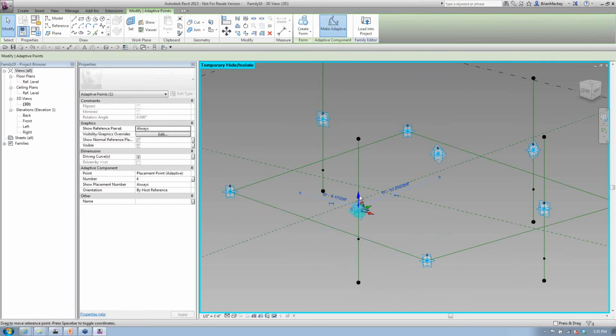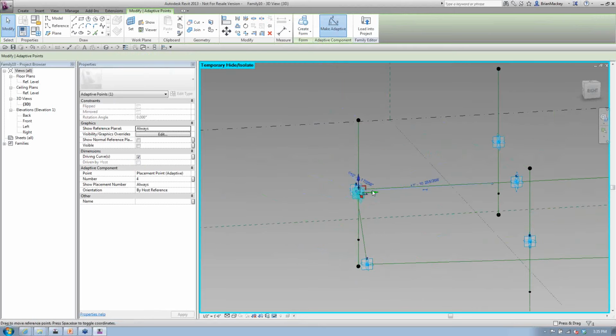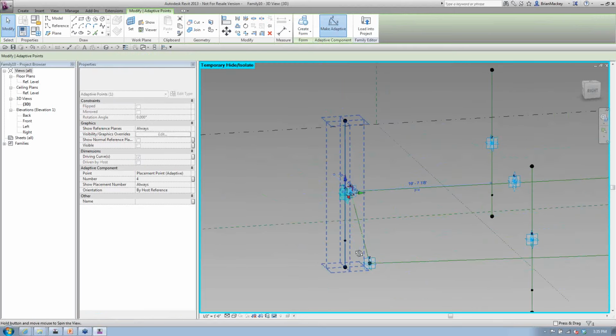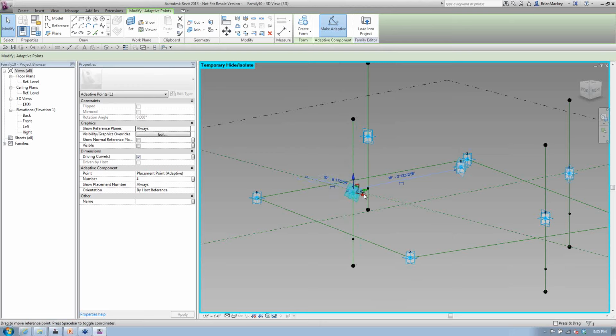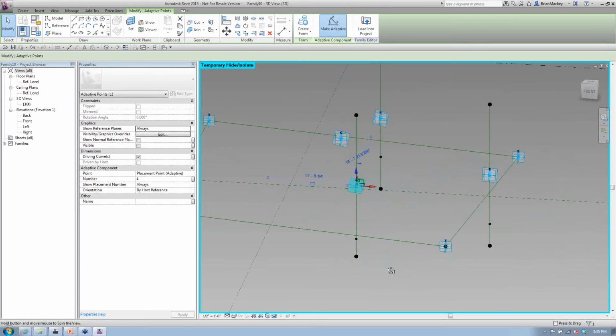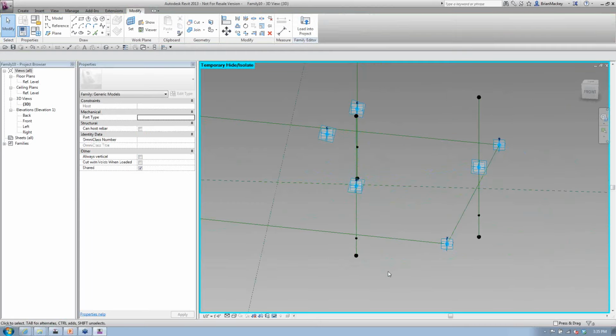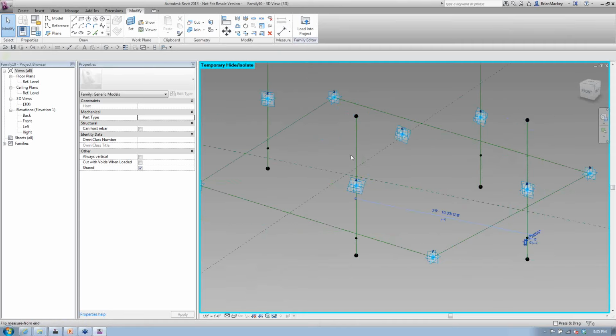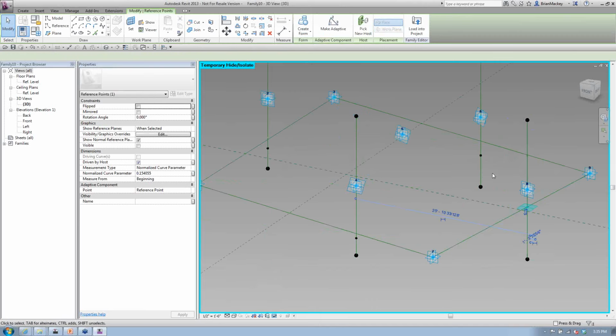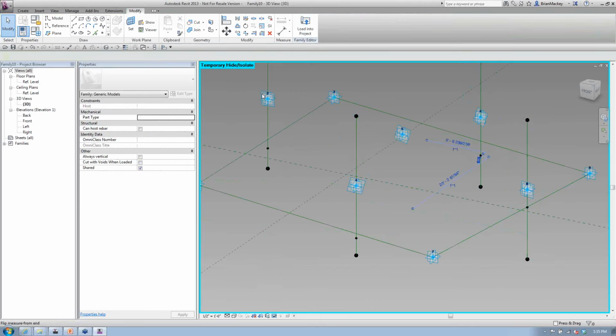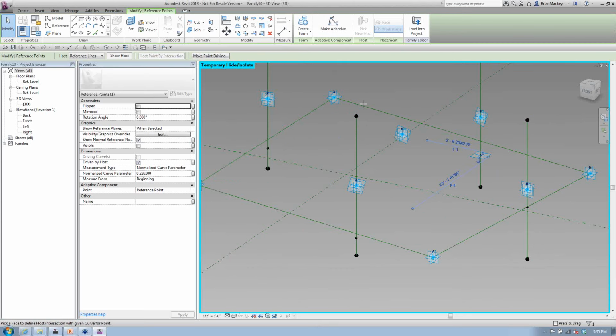So now when I start coming in here moving this up and down, that's not just staying where it is, and even if it's out too far, it's understanding I'm hosting on that work plane, moving up and down with it, moving side to side. It's all doing what I need it to do. And of course I have the panel hidden, but in the background the panel's changing shape and getting deformed as well. So I'm going to grab each one of those points and say host by intersection. Grab this point, host it by an intersection, and grab this point and host it by an intersection.